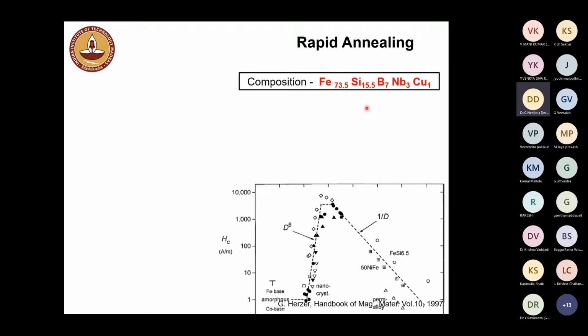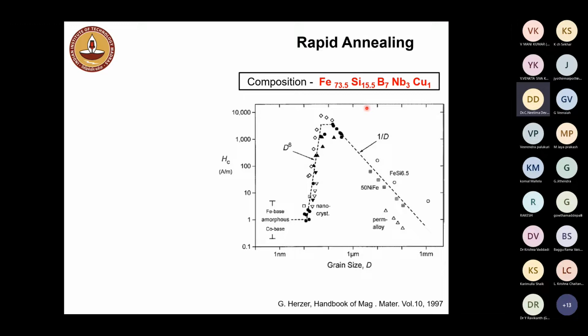The purpose is like this: the physics of nanocrystalline materials indicates that when you produce these kinds of materials in a grain size of millimeter, you can have the lowest possible coercivity. But if you lie in a range between millimeter to micrometer, the coercivity increases dramatically. That means this cannot be a soft magnetic material with high efficiency. But on the other hand, if you get into the nanometer regime, that means you reduce the grain size of this combination of elements in the range of, for example, 10 nanometer till 5 nanometer.